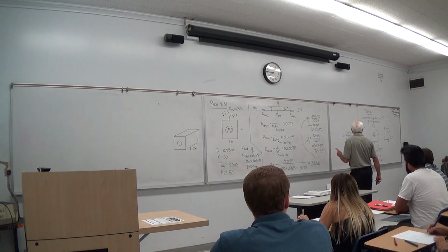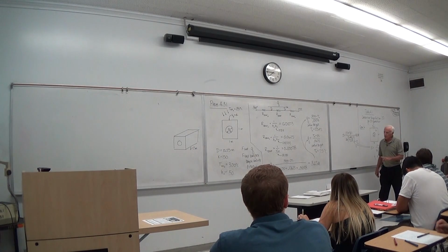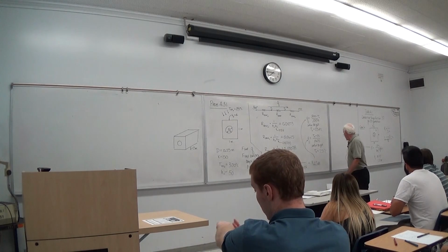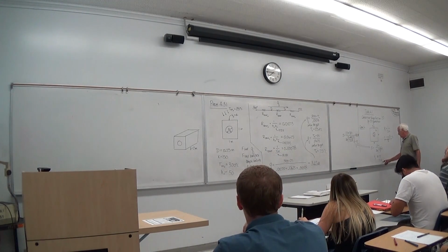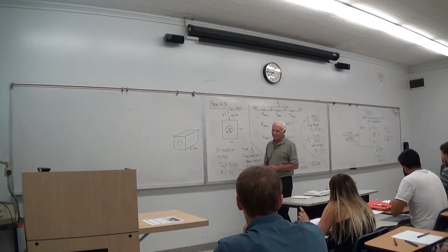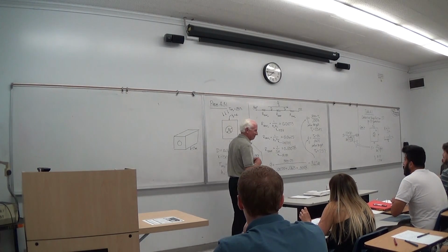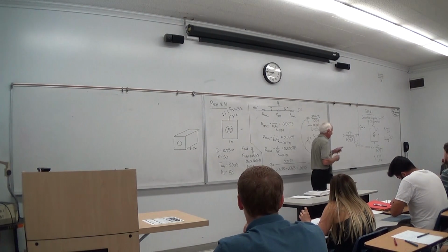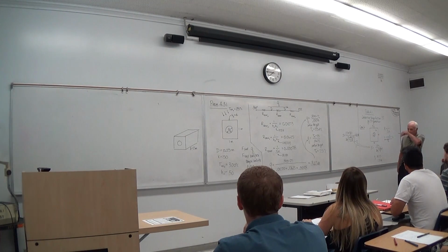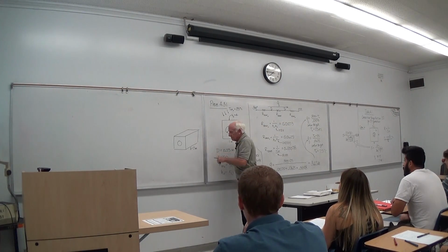Okay, did we satisfy the conditions for S? Was W greater than D? W was 1, D was a quarter. Yeah, that's right. Is L much greater than W? L is 2, W is 1. No, not really. Much means like 10 to 1. No, I'd be cautious of this solution. If L was 10, I'd say fine, no problem.